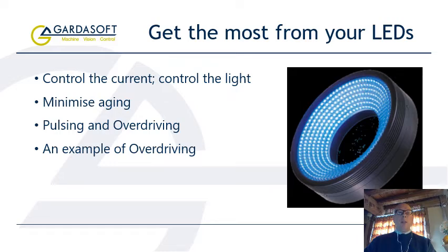Gardasoft has developed SafeSense technology to impose safe working limits on overdrive based on manufacturer specifications, pulse width, and duty cycle. SafeSense technology also ensures that the maximum current rating for the LED is not exceeded during continuous operation. The heat generated within the controller itself must also be controlled, and Gardasoft designed its Safe Power technology to minimize the heat dissipation in the controller by automatically adjusting the lighting supply voltage. This allows lighting to be driven with high continuous currents without heat sinking the controller.